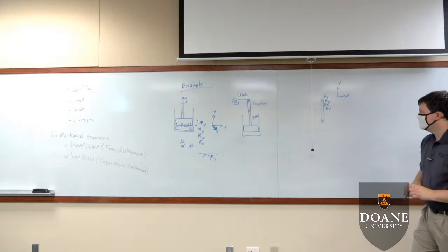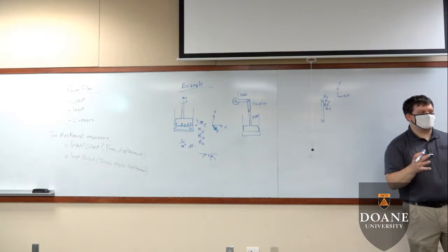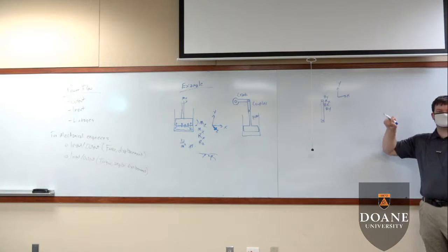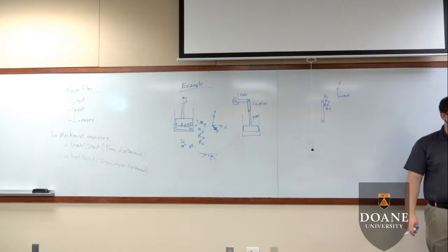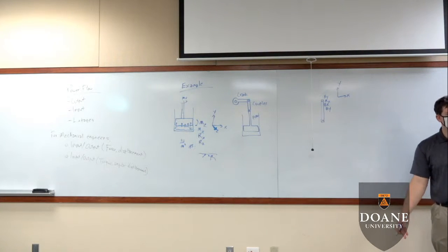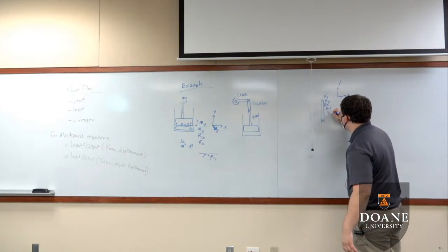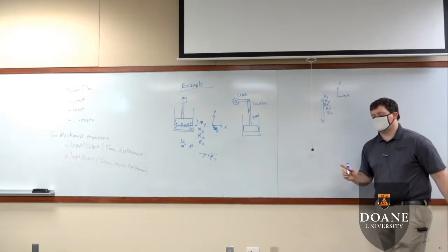Okay? Now, if you have a bolt head on your revolute joint, it will prevent it from sliding out in the z direction too. If this is just a round pin, it does not have an Rz value to it. You could just slide it straight out. We're going to assume that it does have a bolt head and a nut on the other side. It's basically sandwiching the joint. And for that reason, we're going to be able to apply an Rz value. However,